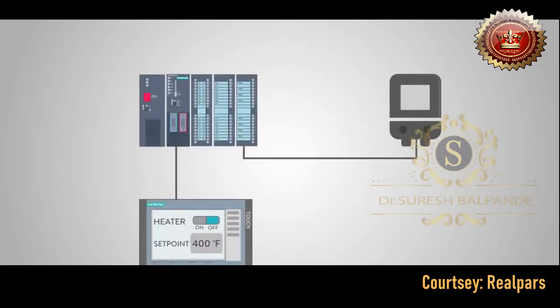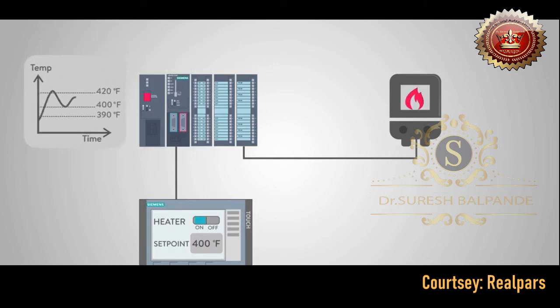A common industrial PID-controlled item is a heater. Many systems in manufacturing plants have to be heated. We control this with a PID block within the PLC. When a set point is entered, the PID will determine when the PLC needs to turn the heater on and off to maintain a constant temperature.